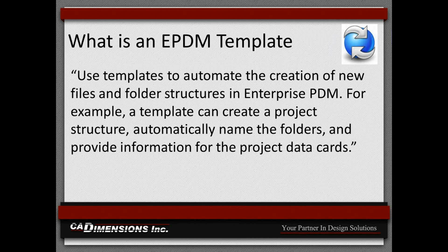Templates in Enterprise PDM automate the creation of something. I use that as a general term because they can automate the creation of folders in folder structures. They can automate the creation of a standard document. Let's say you have a spec sheet or a budget or a SOLIDWORKS template and you want to automate the creation of a SOLIDWORKS file. You can do that through an EPDM template.